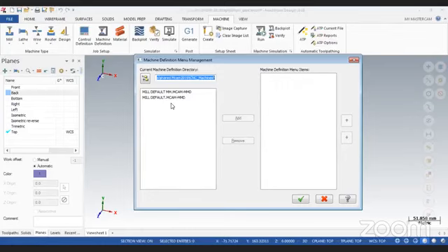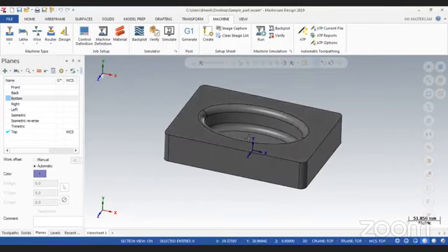And I just need to go through that specific machine detail. And then the program output which will be generated by Mastercam will run in that specific machine. So at initial stage, we need to define in which machine we want to manufacture this particular product. After that, Mastercam will generate a program which will be adopted by that specific machine. So that will be a post processing process.